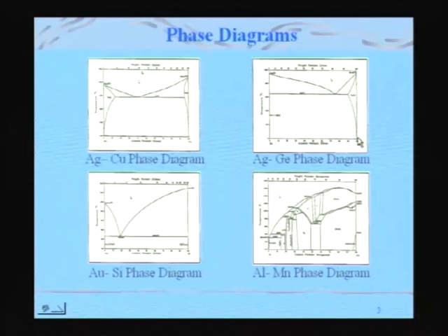the phase diagrams. So it is possible that they exist as clusters in the liquid, and when the liquid is cooled rapidly, instead of the equilibrium phase coming out of the liquid, the non-equilibrium phase can come out, because the activation barrier for that non-equilibrium phase may be very small. For example, as we see in case of age hardening, we know that Al2Cu does not come out, but the GP zones, theta double prime, theta prime, all these phases come out.